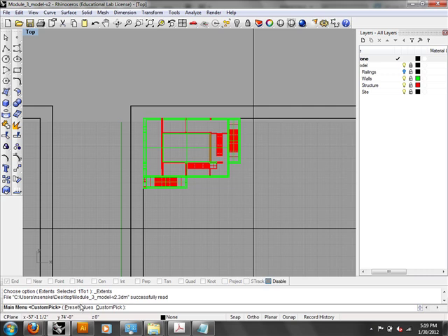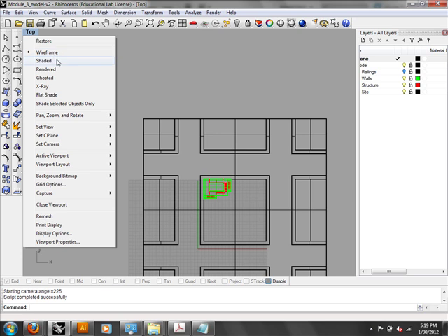Let's go ahead and click preset values, and now here you can select what angle the x-axis is. So 30 degrees, and I can just press enter, or I can type it in, and then what angle the y-axis is, and I can also say 30 degrees, and then the z-axis. I think you probably want to say positive most of the time. I think it actually knows auto. Z-axis is which direction is up. Hit positive. Camera rotation, I can also type in the rotation I want. Show camera line. No. And what that actually produces,